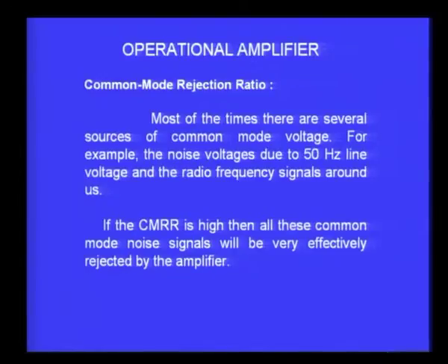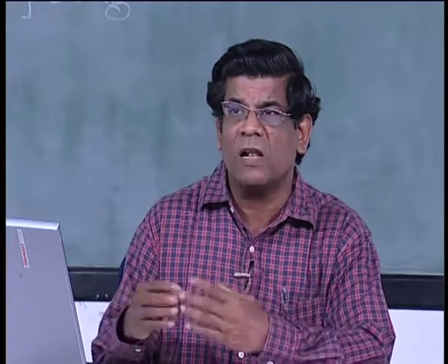In principle, it will also be amplified. All these noise voltages also will be amplified along with the signal, which is the only thing that you want to concentrate on, and therefore the output will have enormous voltages coming from these noise voltages. Sometimes the noise voltages can completely swamp the signal that you wanted to observe. Then the signal will get buried in noise and you will not be able to see the signal very clearly.